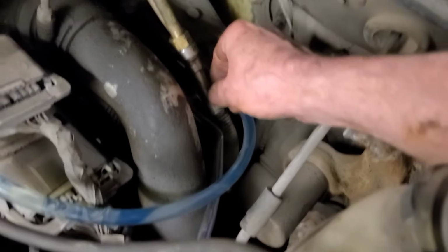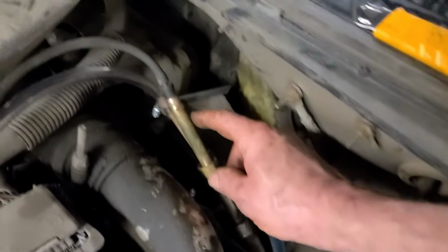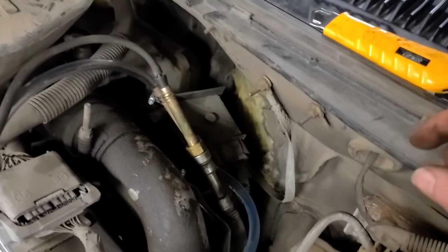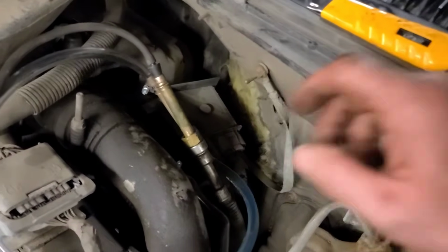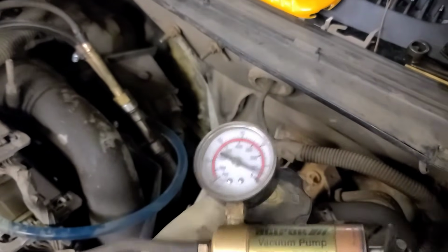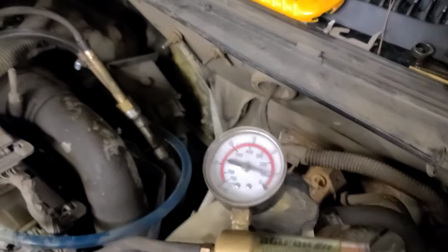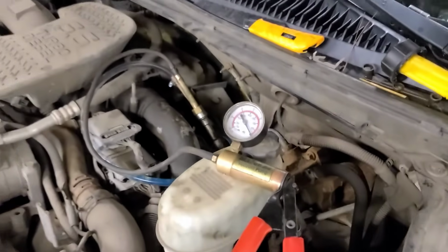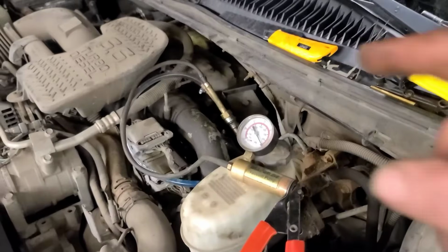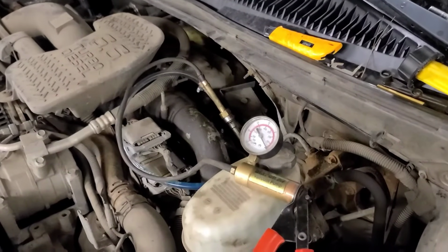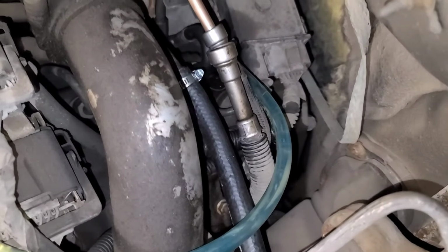I don't think it's these O-rings. I took that coupler off from down below and I checked it there. I cut the pipe about 1 foot away where it was nice and clean. So somewhere between here and the cooler down there, there's a pinhole in the line, and yet it doesn't seem to leak. You would think if I put pressure on it, it would leak fuel out of it now because there is fuel in the line. So I'm going to run a new line right from here to the tank connector and then see if we can prime it. So there it is, back together and running again.